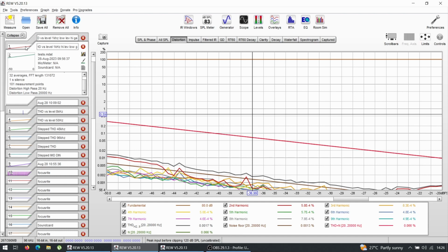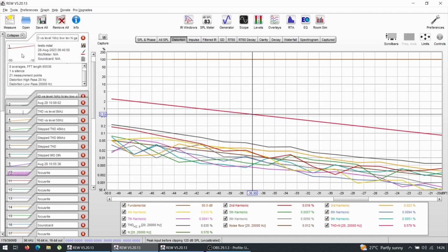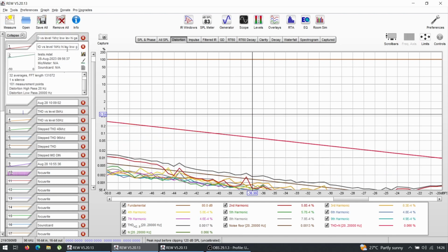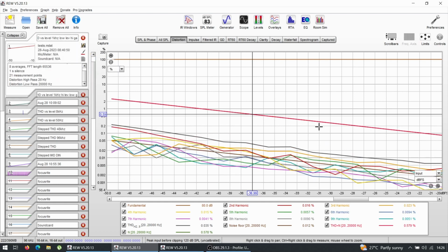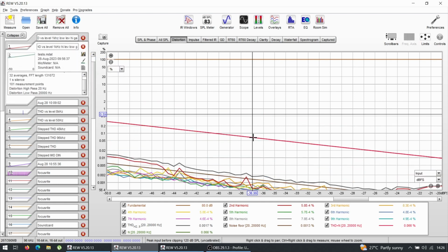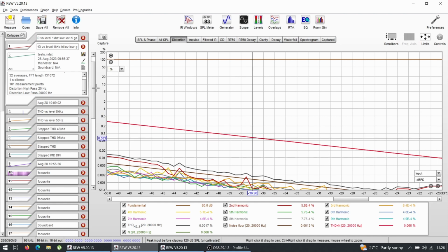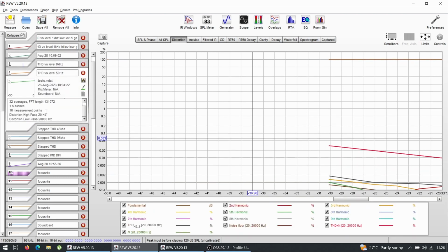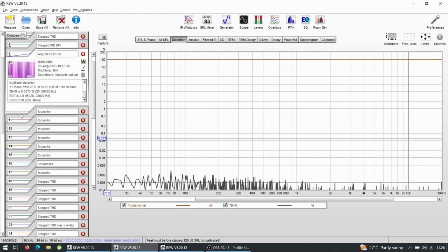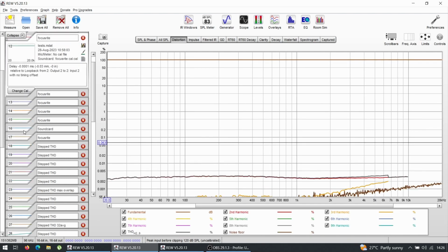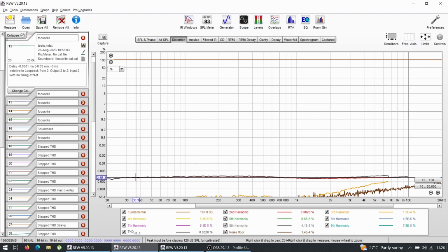So that means that in order to have more accurate measurements with lower THD from the actual sound card, I need to keep the level as high as possible and the gain on the input, the microphone input, input 1, as low as possible. Then I will get the lowest THD from all these measurements. And I did play with loads of different stuff. I was checking THD versus different frequencies, multitone, sampling rate. I was playing so much with this, like the distortion of this audio interface.